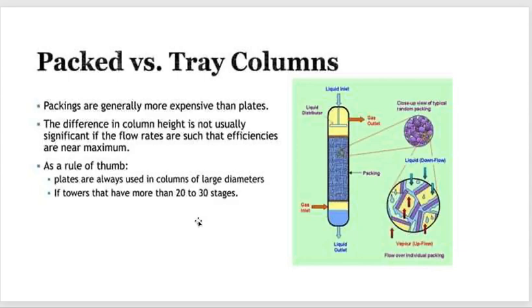If the tower has more than 20 or 30 stages, it is recommended to go to the tray tower, because you cannot transfer this huge number of trays into packing. As we mentioned in the calculation, the number of trays will be switched to diameter and height.